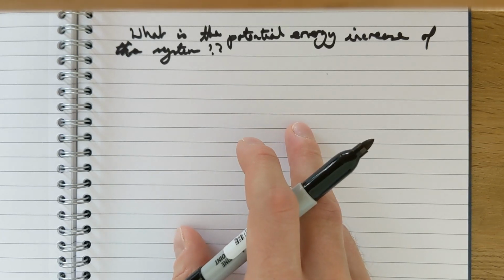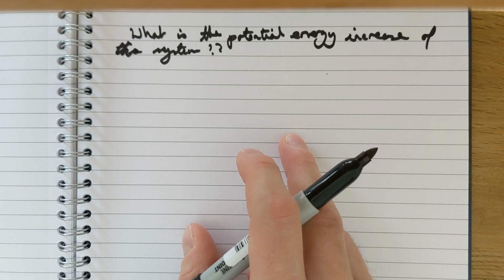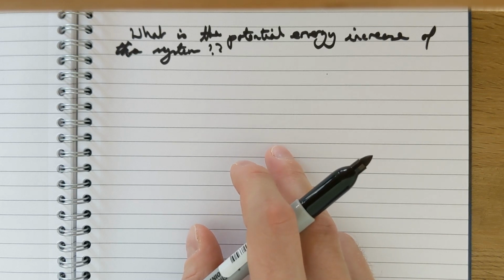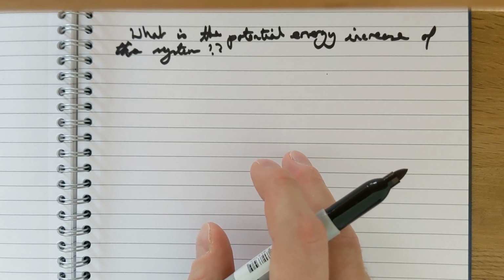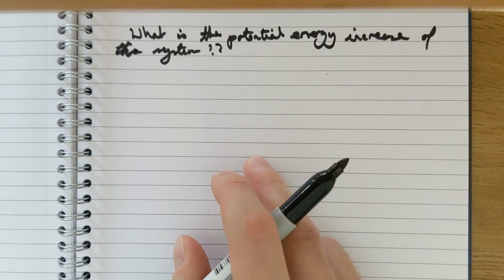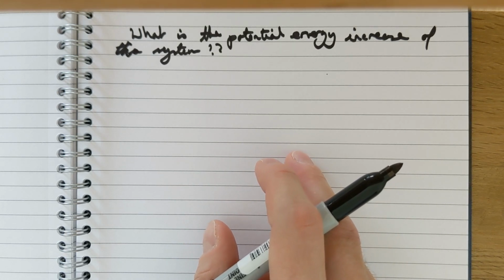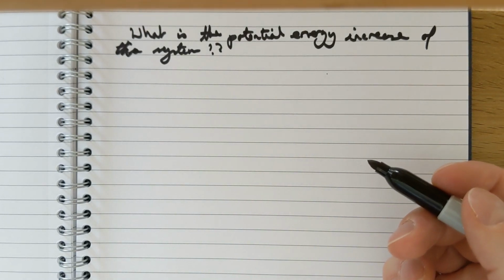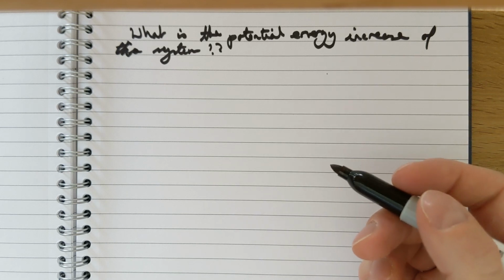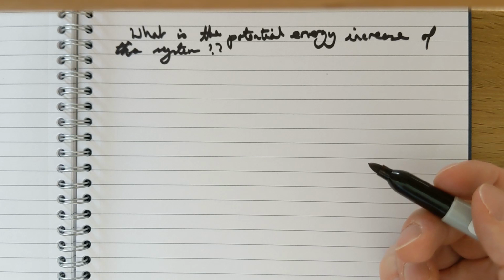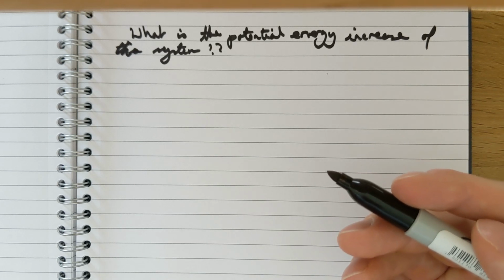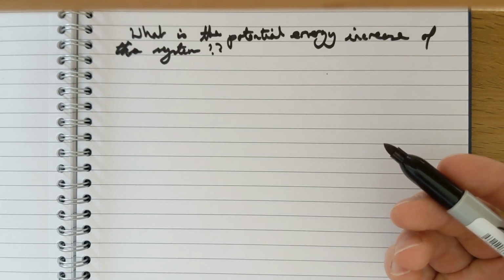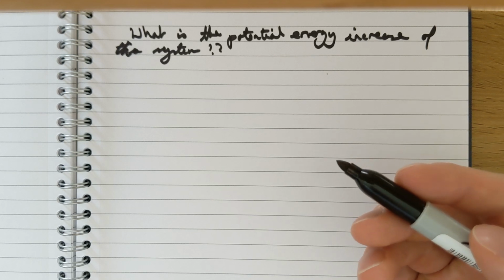Per unit was used a lot in power systems engineering, and we'll get on to explain why that is and the benefits of the per unit system. But in short, the per unit system was used a lot and is to some extent still used in power systems engineering because there's a lot of arduous calculations that need to be performed, and using the per unit system makes these calculations a lot more simple and trivial and a lot less arduous. So it's really a mathematical tool to make the calculations simpler, even though they could always be worked out with the true values.